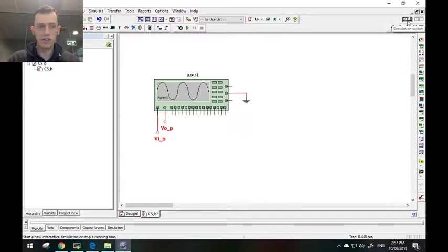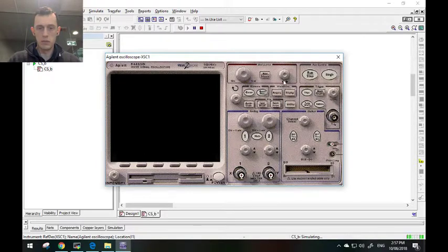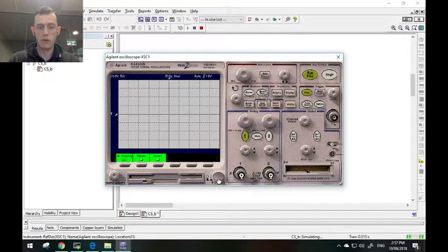There's no other changes to the setup, so we just start running. What we'll do is turn the power on for this device. Number 1 is automatically there. Its coupling is DC. And for number 2, we need the coupling to be AC. Now we'll also press auto scale. That'll help us a bit, and we should now be able to do a measurement.